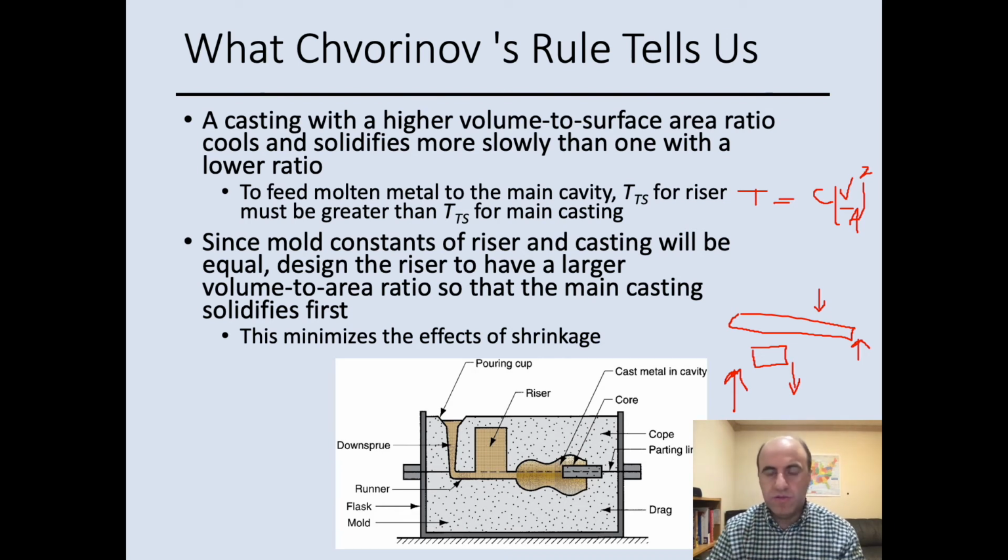This is important because we can use this equation to find the volume to area ratio for the riser. Because we want the riser to solidify after the part, it should still be in liquid form when the part is solidified. So if you want to have the riser in a liquid state, you should have a volume to area ratio with a lower value.